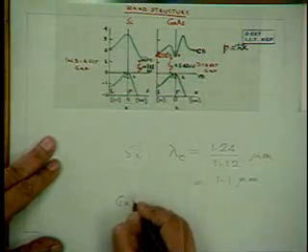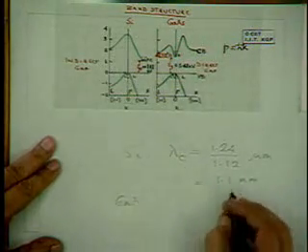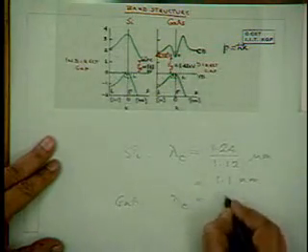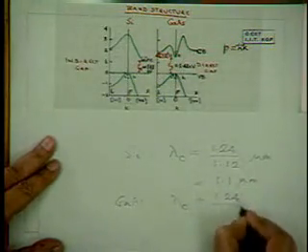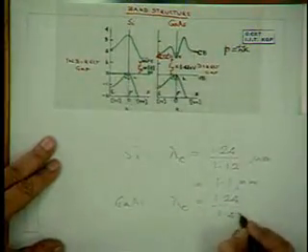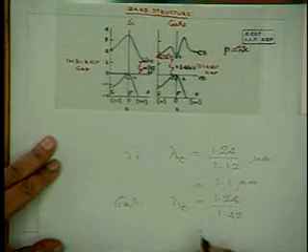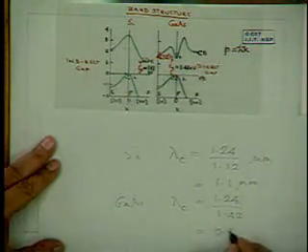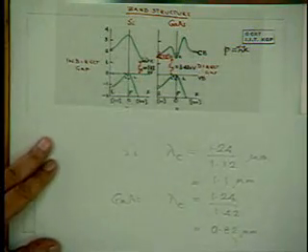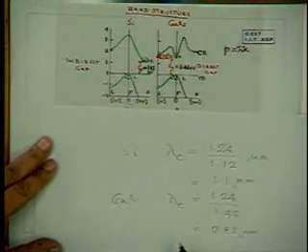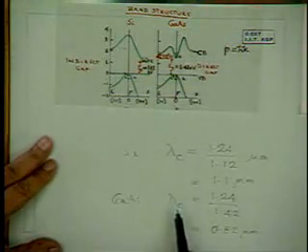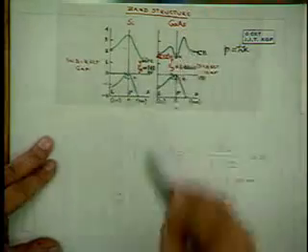whereas for gallium arsenide, lambda c is equal to 1.24 divided by the band gap, which is 1.42 eV, which makes it about 0.82 microns. So for any semiconductor, the fundamental absorption starts at an energy which is just equal to the band gap of the semiconductor.